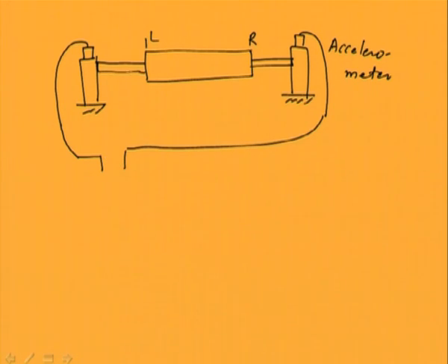Then on the shaft we can have one photoelectric probe, which senses a tape attached to the shaft, and that is a reference position through which we will be measuring the phase all the time. So, this measurement also is here. Basically we have three sensing devices: two accelerometers and one photosensitive probe as a reference signal.